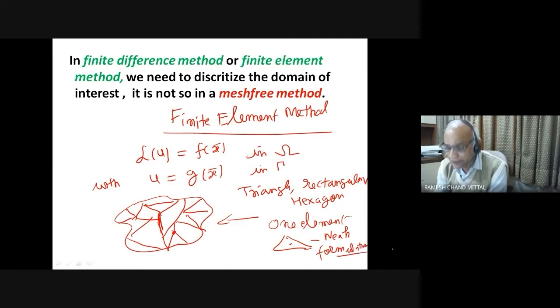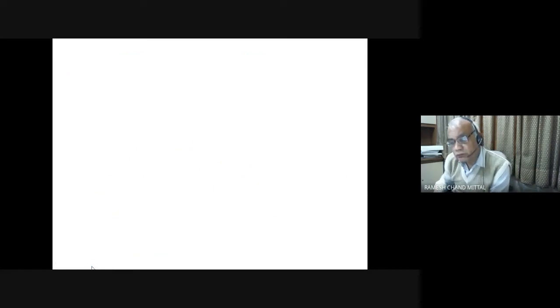Because finding the solution in strong form is rather difficult. Now, for those of my friends who do not know what a weak formulation is, a weak formulation means we assume a solution which may not have that kind of continuity and differentiability as the differential equation desires.